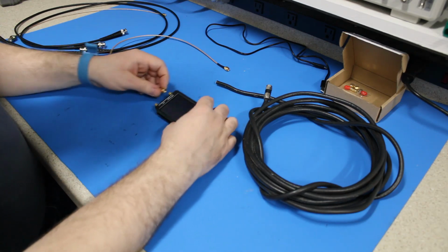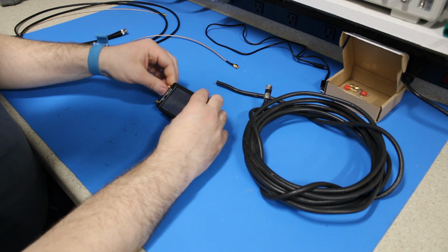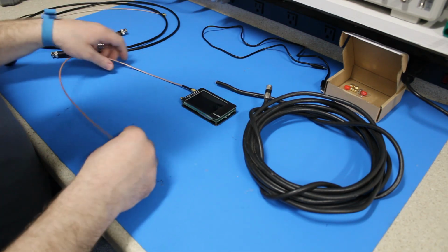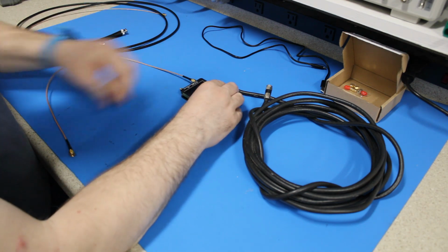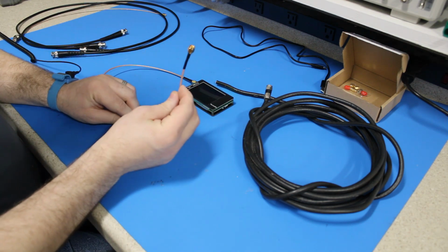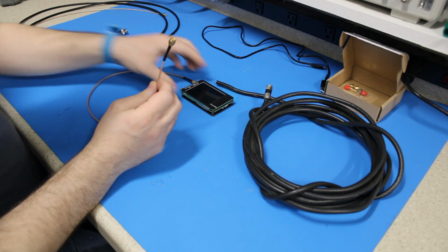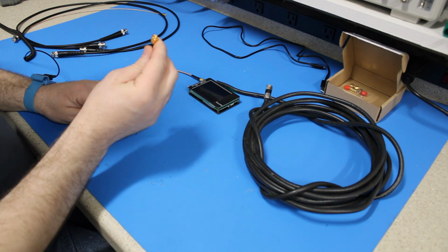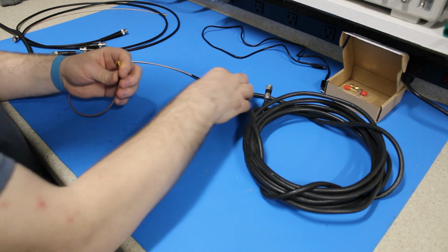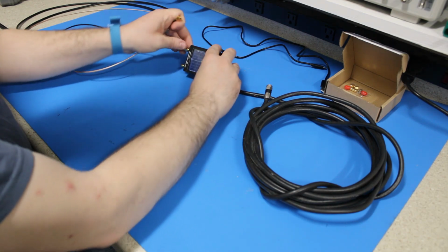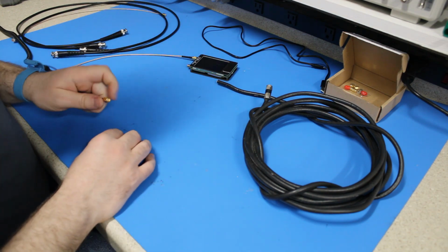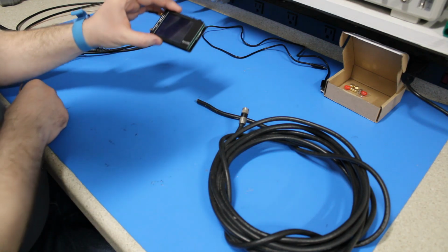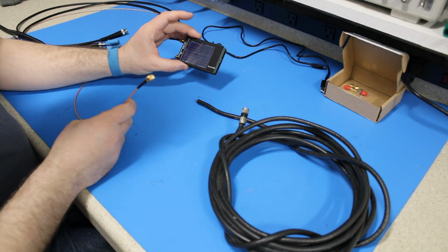Alright, so to begin with, we're just going to be using port 1 of this, and you always want to calibrate your device before using. This one in particular has already been calibrated. The reference plane that I'm using is the end of this SMA cable, right? So right now there's no phase on the plot because nothing is connected. It's as if this is the end of the measurement device. And what I'm going to do is simply take a measurement of the cable, and I'm going to look at the phase on a single port measurement.